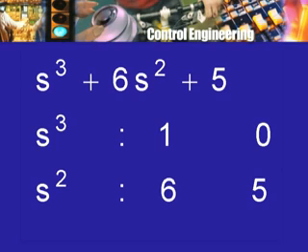So, the first step in the construction of the Routh array or the table is to write down these two arrays correctly. Let us take an example that I mentioned earlier, in which one of the coefficients was equal to 0. What happens in that case? Of course, I told you that it is a bad polynomial, and Routh rule tells you also something about it. In that case, the polynomial was s cube plus 6s square plus 5. So, let me split it into its odd part and even part.